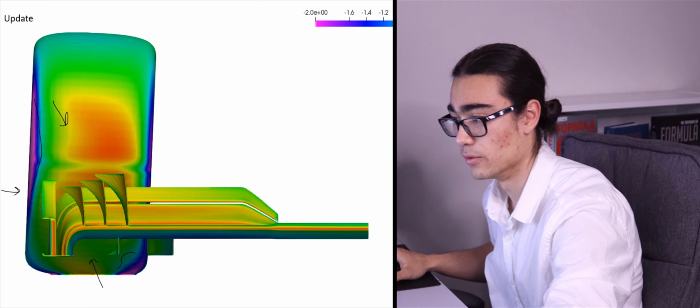When we've got an area of really high curvature, like around the front edge of the wheel, and a very low pressure on it, we can usually say that there's some flow passing over that outboard edge, but we need to remember that because it's creating such a low pressure, it's likely to be quite high energy flow. So just because there isn't a low pressure on a curved surface doesn't mean that air isn't passing over it. It could just be very, very lossy air, and so we're not seeing the full effect.